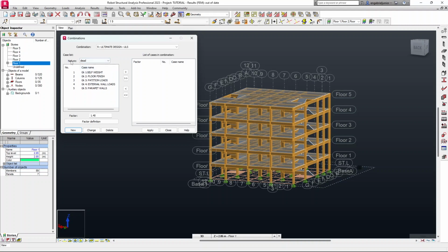So as you can see, immediately I've changed it to dead load. It's going to give me 1.4 for the BS code. I can decide to edit it, perhaps 1.42 or 1.5, but I'll keep it 1.4. Then I assign them, clicking on this side. Then I go to live loads, 1.6, send them, so they've been factored.